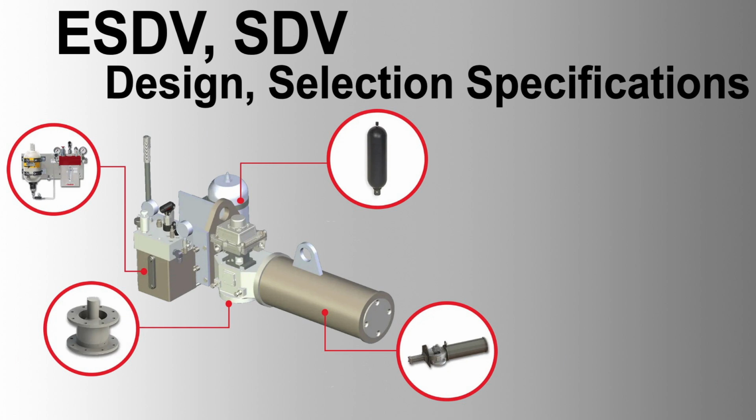Shutdown valves. Function: shutdown valves, SDVs, are used to isolate specific sections of a process or equipment for maintenance, testing, or during abnormal operating conditions. They can be operated manually or automatically. Application: SDVs are typically used in process lines, utility systems, and equipment isolation points to ensure safety and facilitate maintenance without disrupting the entire process.